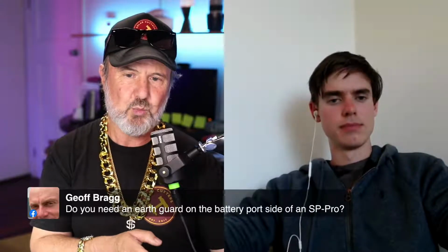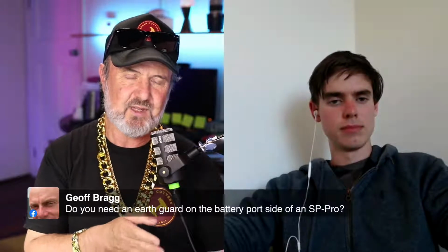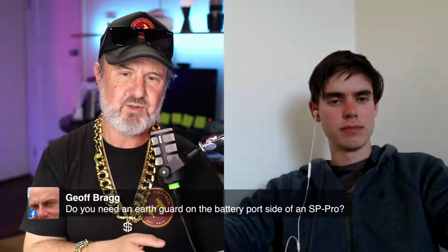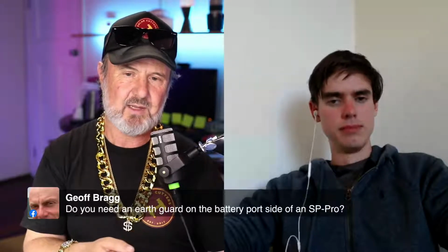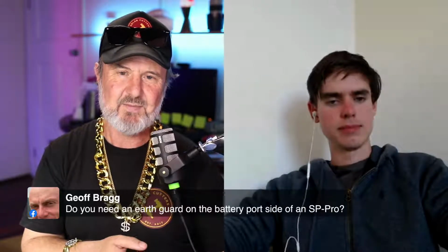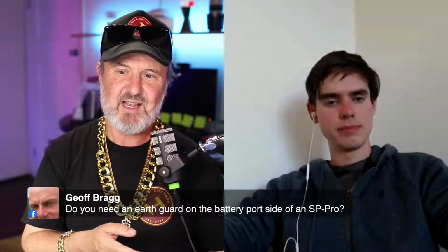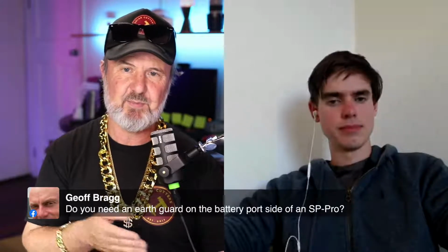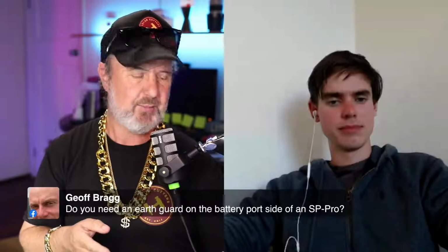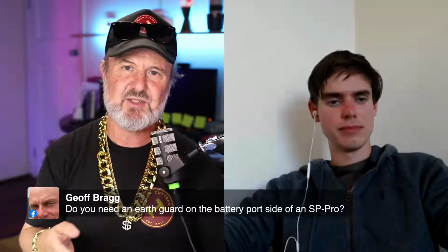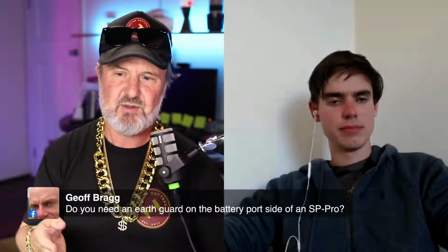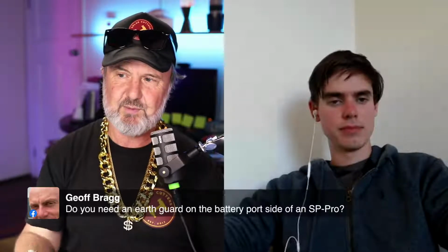So it depends on what source of PV charging you have connected to that battery. If it's AC charging from a galvanically isolated SP Pro, then you don't have that potential for the earth fault because it's galvanically isolated. But if it's charged through an MPPT, then you do. Now, do you concur, Peter?